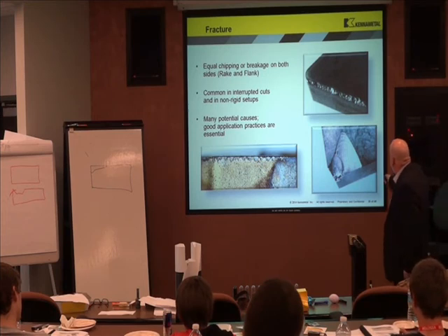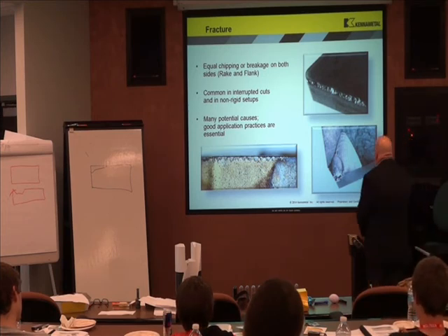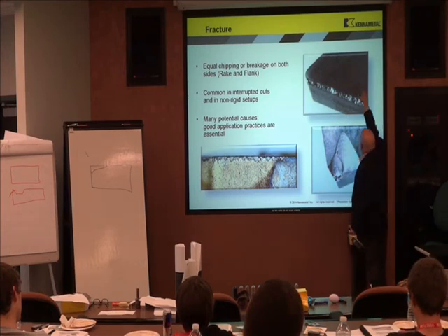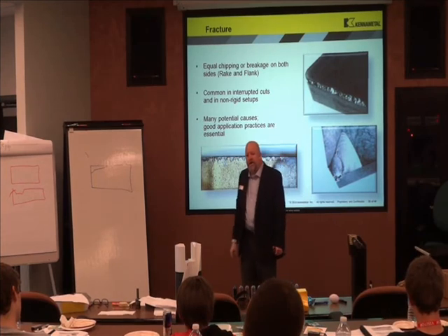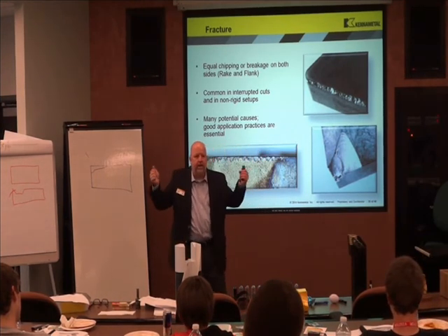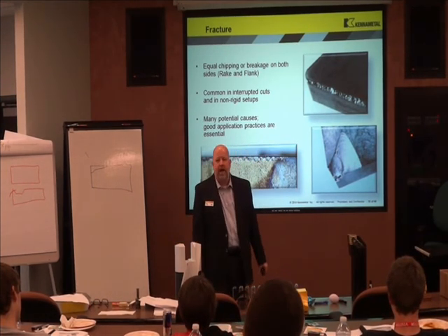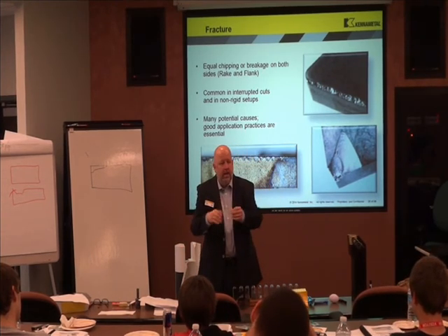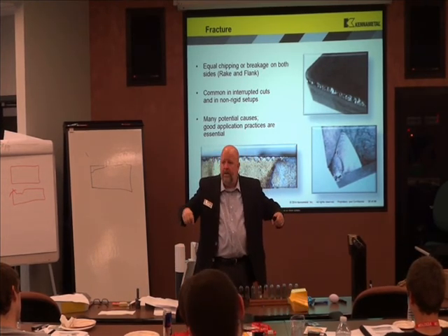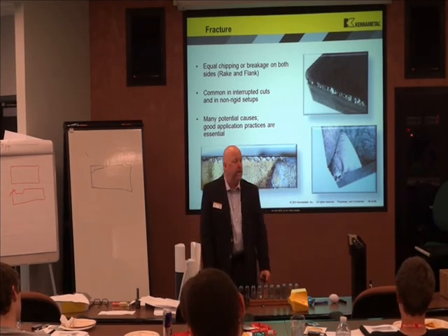Sometimes I get chippage that is equal on both sides. It's not wider here. It's not wider here. If the chippage is equal on both sides of the cutting edge, it typically means something's vibrating. You're getting chatter. The only thing you can do is shorten your tool gauge length, tighten your fixtures down, make sure everything's as rigid as you possibly can.